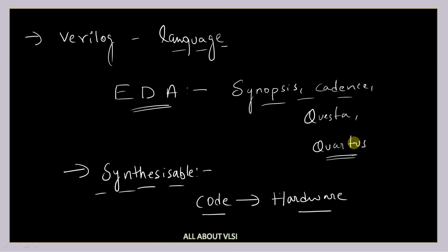So a developer or programmer who knows Verilog should be very careful about what he is coding for: whether he is developing his code so that it should be converted into a gate level netlist, or he is just writing his code for simulation or testing purposes. And if you use both synthesizable and non-synthesizable constructs, definitely it is not going to be implemented on any hardware.